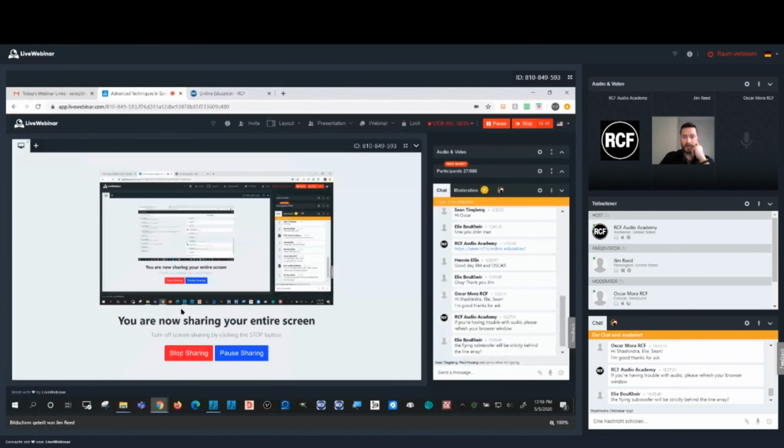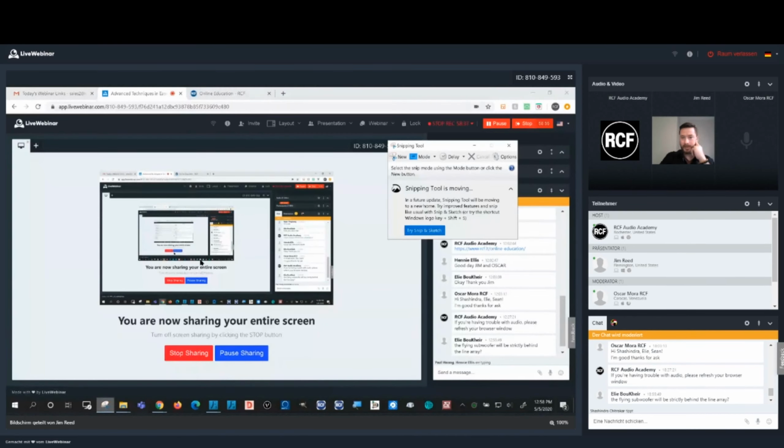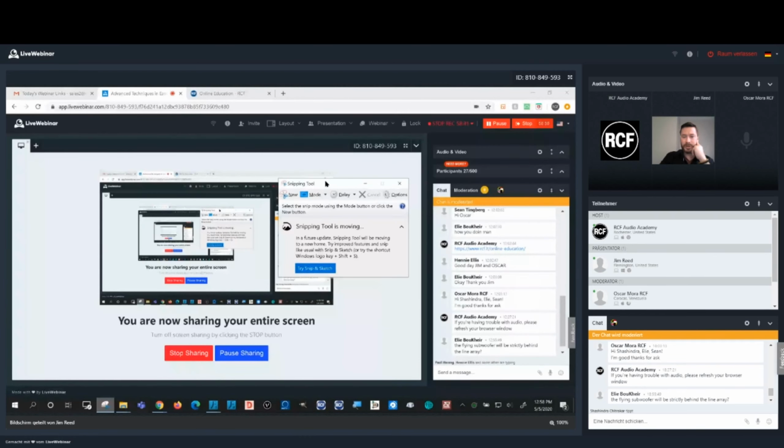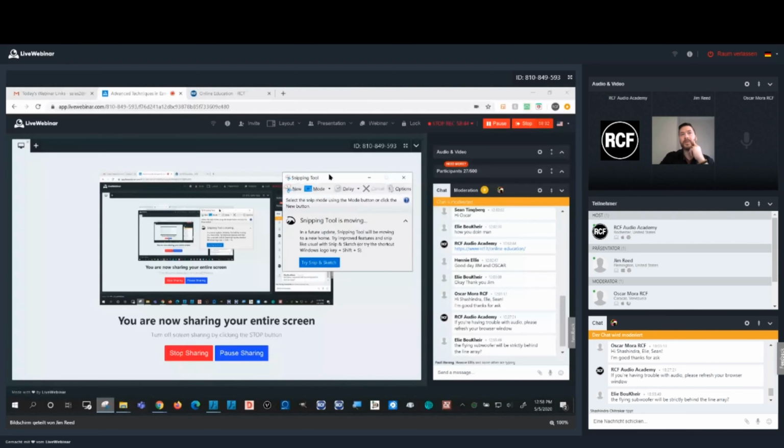Yes, I am. On PCs, there's a built-in tool called the Snipping Tool, which allows you to take a screenshot of what you need. So take a screenshot of a PDF file or an AutoCAD file, save that screenshot as a JPEG or what have you, and then import that JPEG into EASE Focus.